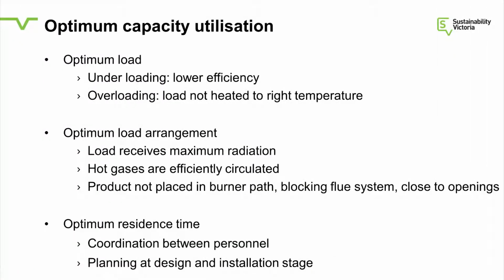We talked about capacity. Clearly, optimum load of the furnace is important. Optimum residence time in the furnace, you need to plan that properly. All of those things you'd think would be common sense, but often people will not load the furnace properly and will not control the process as well as they should.